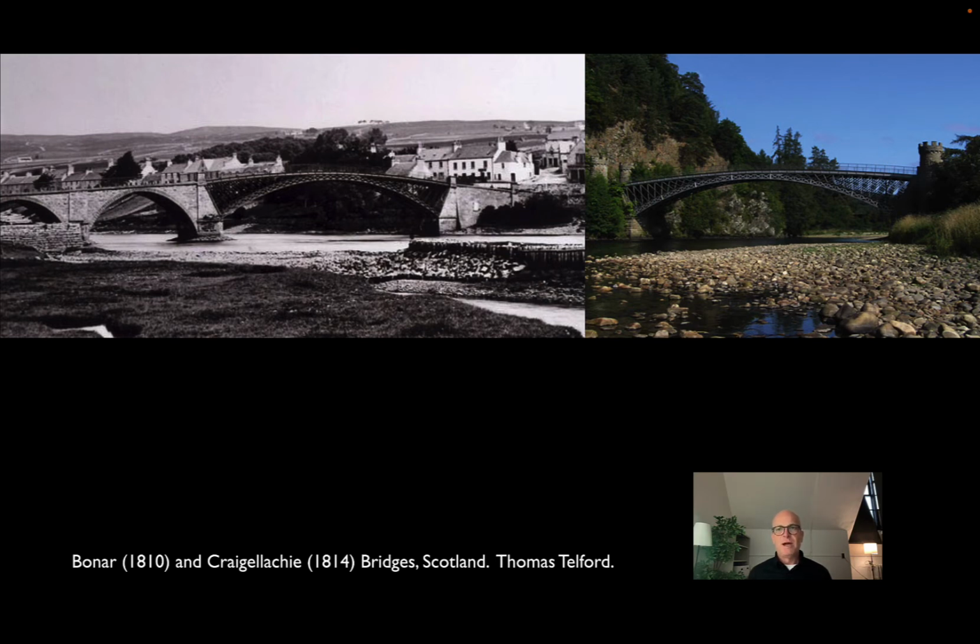And then his real genius was to understand that by connecting the two, you could make the bridge behave in a more efficient way. As we were talking about concrete, this is a way of making cast iron, if not monolithic, at least hyperstatic. Connecting the deck and the arch means that loads have millions of different paths they can follow as they reach the abutments. The deck and the arch are working together, essentially.